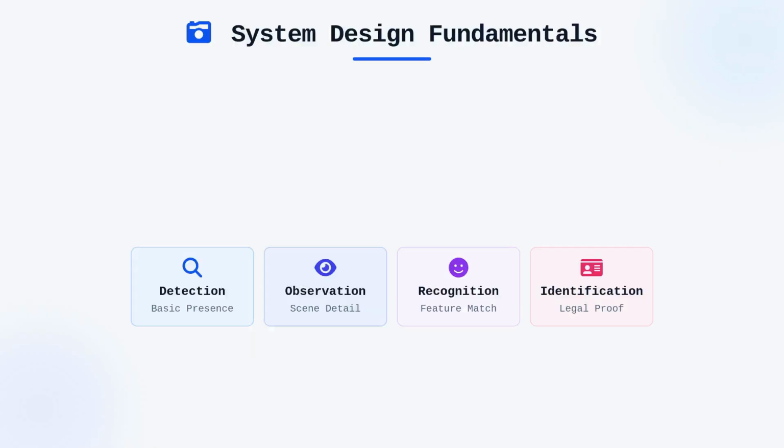When approaching system design, the intersection of pixel density and lens focal length remains the fundamental starting point for any successful deployment. We have learned that the DORI standard, covering detection, observation, recognition, and identification, provides the necessary metrics to ensure that design expectations align with physical camera placement realities.